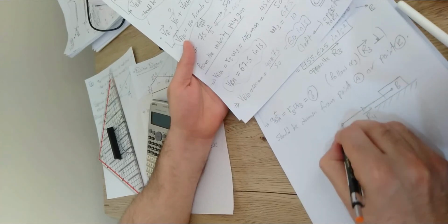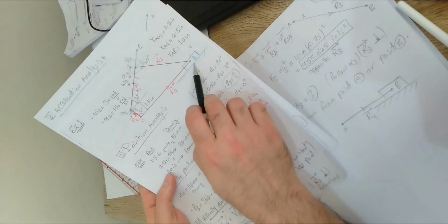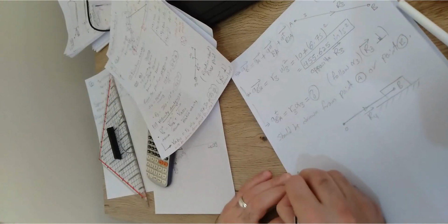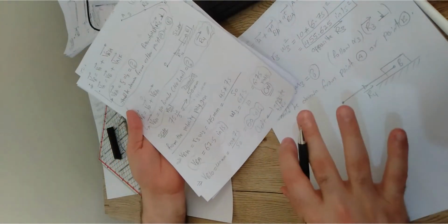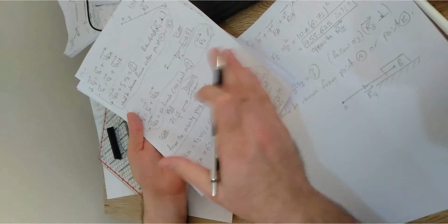R4 vector, and this R4 is set up between 2 points in the mechanism as already given here, which are point O and B, right? So we already have R4. For this length, the equation is typically the same as the equation of the velocity analysis for the same slider. Here there is no normal, there is no tangential because there is no rotation. This R4 won't be rotating, right?